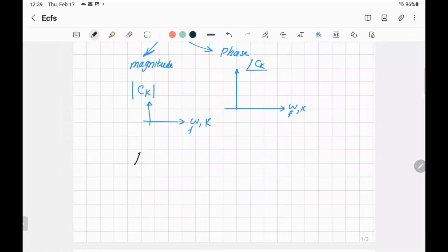The power of any signal x will be equal to the sum from k equals negative infinity to infinity of the magnitude of ck squared. That's all. It gives you the power. You give it as a sum, you program it, and then you calculate it. Again, when I solve problems, I found it's better to separate C0, so I make C0 squared, and then I do the sum.